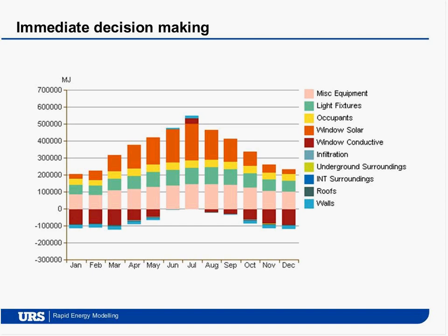Once we run the 3D model through the energy simulation, we get a whole range of results. It gives the headline results you'd imagine in terms of kilowatt hours per square metre of electricity usage, so the energy usage of the building, the conditions of the building, but it also shows things like a seasonal breakdown of energy use.